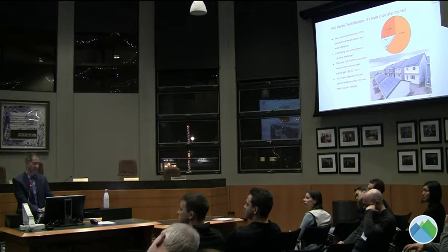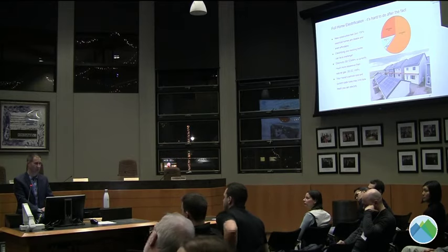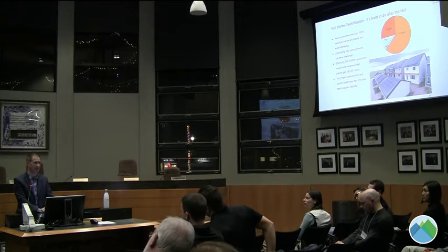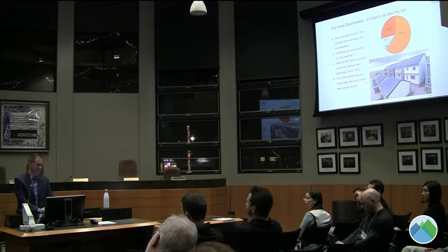Very final comment on electrification is your home's electrical service size and current CEC, Canadian Electric Code requirements can actually limit how much you can electrify. They might say, yeah, no, you're not putting all those loads on that service. It's X grand, it's a lot to up the service size.